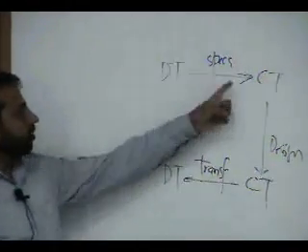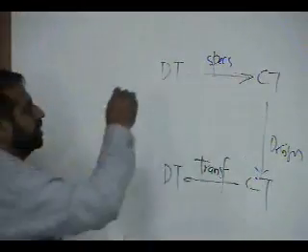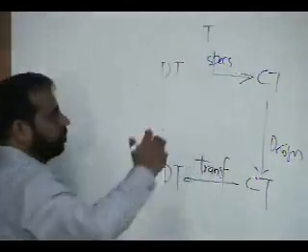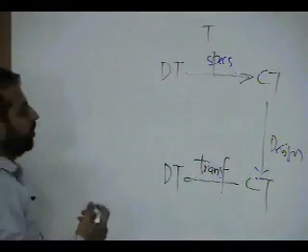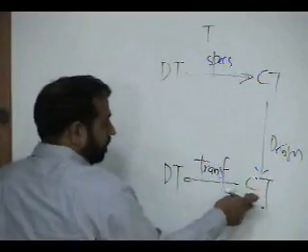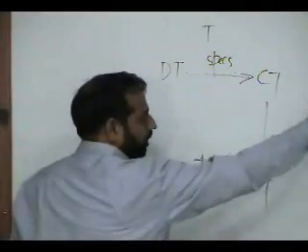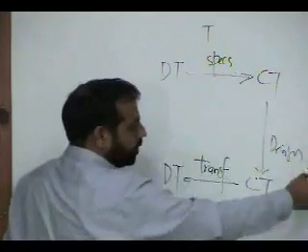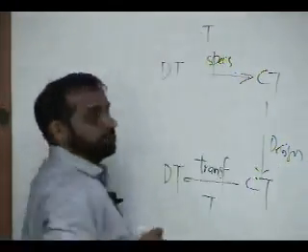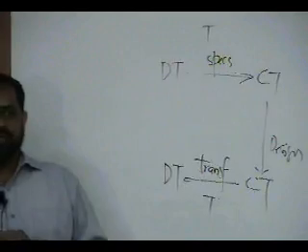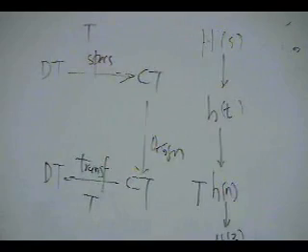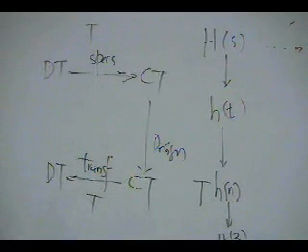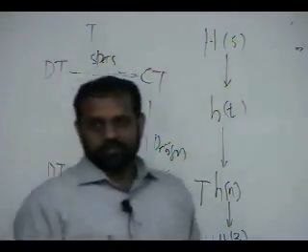Once you go from the specs, you need to specify a capital T. It's up to you; you can keep capital T whatever value you want. Then once you come back from continuous to discrete time, through the sampling, you again need to specify T. This T must be the same as this T. If these are the same two T's, then it does not really matter what the value of T is. For example, if I say 5 rupees is equal to $1, I don't mind converting dollars to rupees and rupees back to dollars. It will come back to be the same, right?